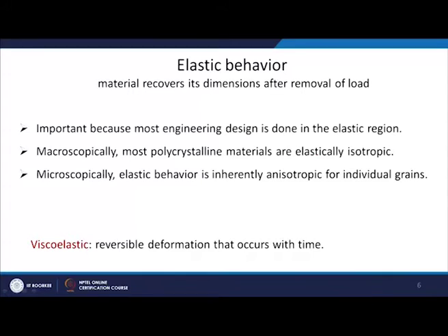Now what is elastic behavior? Once we have defined stress and strain, now we can look at elastic behavior of the material. It is when the material recovers its dimension after removal of load. So if I have applied a load, and when I remove the load, it goes back to its original position.